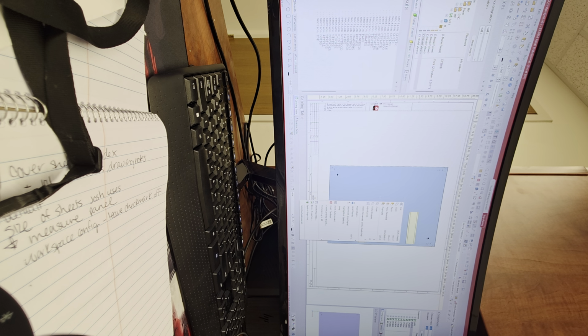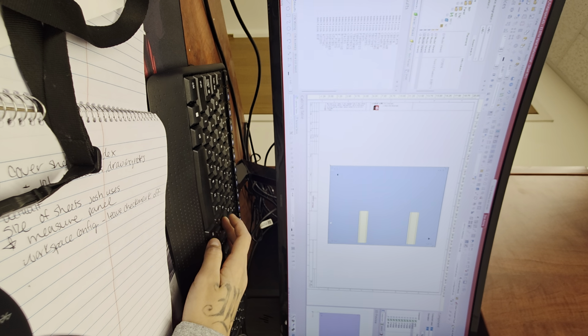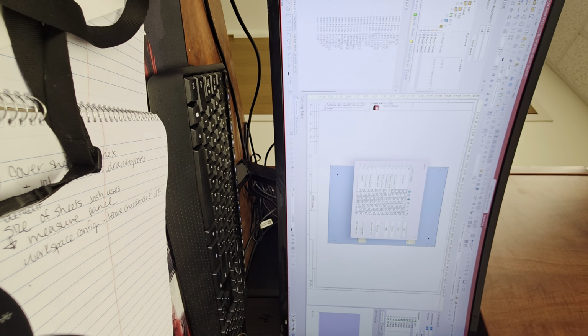And how do you bring it back? If you want to bring it back, right click on the background, anywhere in the background. You don't even have to click on anything, as long as you're on the sheet. Press L on your keyboard for levels, just L for levels. So these are all the 255 layers that you can scroll through. Everything with text is what you were able to see in the drop down menu that you just used. If you scroll all the way to the bottom, there's your hidden panel 254. If you enable these two checkboxes, one for objects and one for symbols, and then click OK, we'll bring them back as a visible layer.